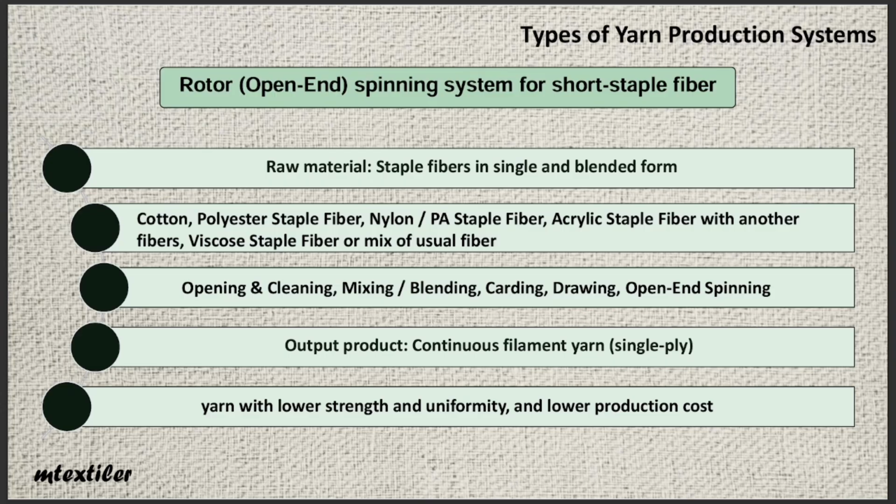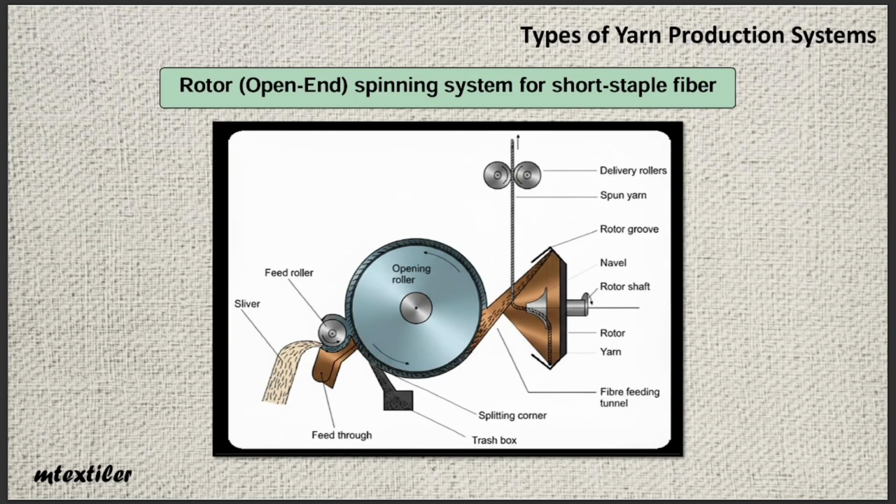In this system, centrifugal force and a rotating rotor send fibers to the edge of the grooved circular surface, and under controlled airflow, the yarn is formed. Here, too, the fiber sliver is fed directly, skipping the roving frame, ring, and autoconer to form full yarn bobbins.